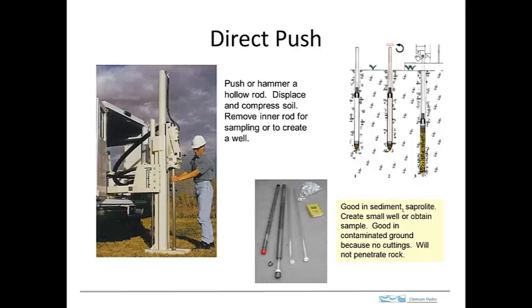There's another technique, though, that's very important. It's not so much important for drilling wells that are used to remove fluids, though, because it can create wells, but it creates very small diameter wells, ones that are much more suited for monitoring. This is a technique called direct push, and it differs from what we've seen with the previous techniques in that it doesn't really remove any of the cuttings. So it's creating a hole, but instead of taking the material that was where the hole is now and removing it from the ground, it simply pushes it aside.